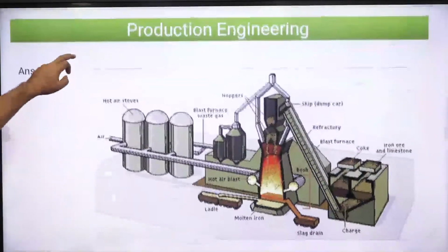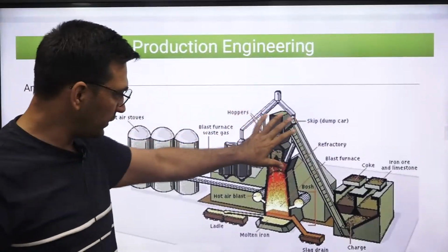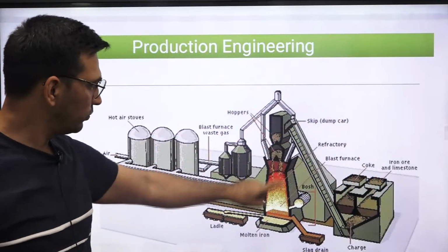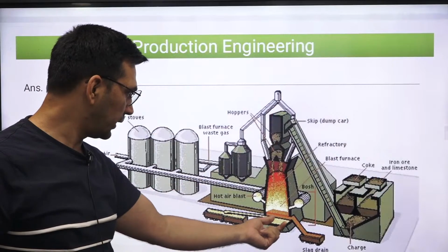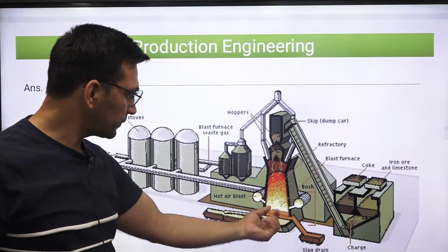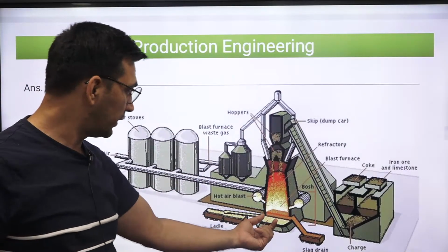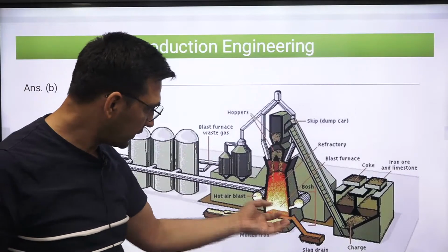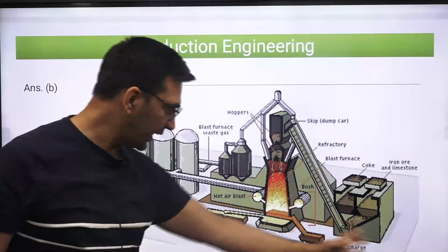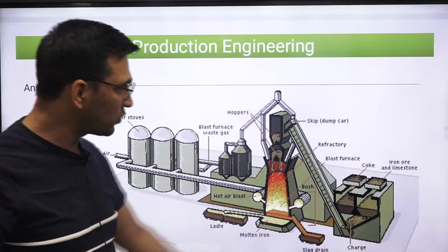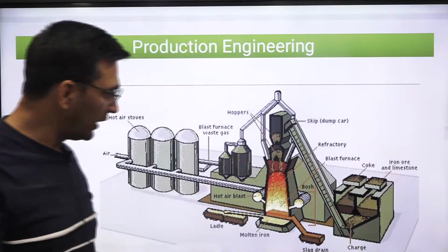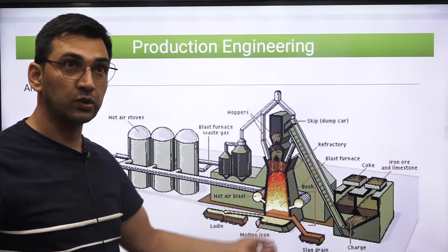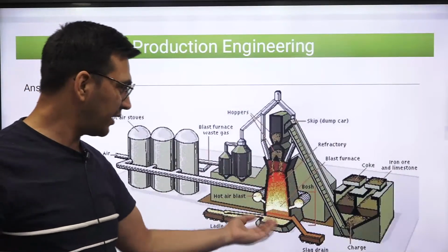Same thing has been shown to you over here. This is a blast furnace where you add the raw material, put it in and burn it. You take the coke, which will burn, and therefore will bring that iron ore into a molten state. After that, the impurities, which we call slag, will be taken out. For that we have limestone added somewhere here, so that will purify it, or you can say it will react with those different impurities, and the lighter slag will be taken out.